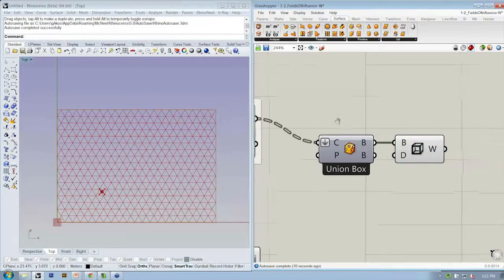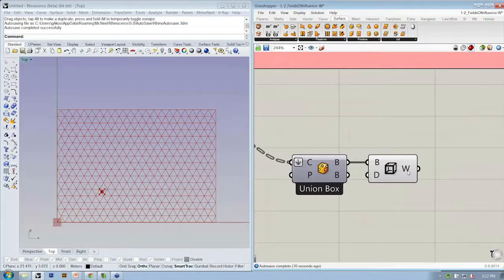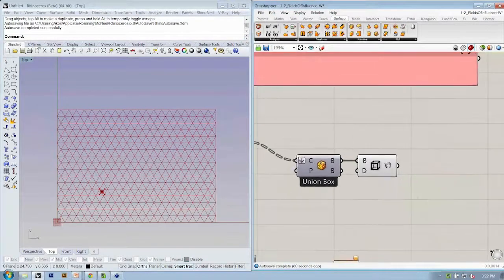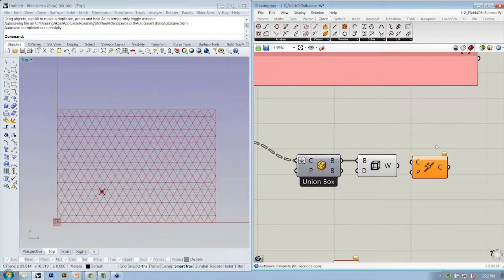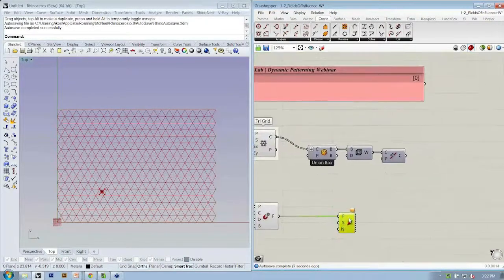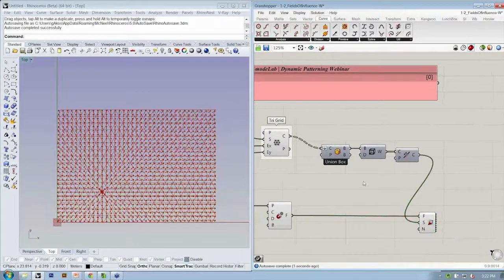All right, so we now have the wireframe of the B-rep, which is just the 4 edge curves, and we need this to be understood as a rectangle. So let's take these 4 edges, these 4 curves, and let's join them together into one closed polyline. So if we go to Curve, Utilities, Join Curves, and as a result, we now have one polyline curve. Okay, now that polyline curve is what's going to go into the section input for our tensor display.